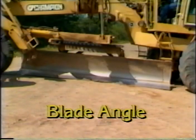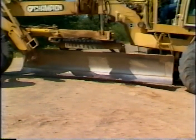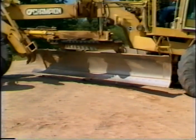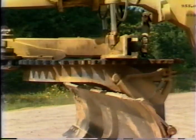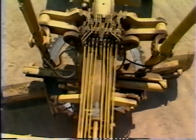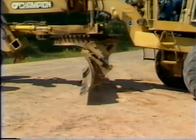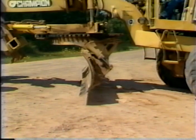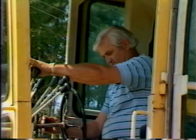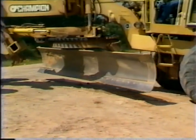The next movement is blade angle. On all graders, the blade is mounted on a circular mechanism, mounted on the center of the grader's frame. This mechanism can be rotated clockwise or counterclockwise throughout a full 360-degree turn. A blade perpendicular to the frame of the grader, or straight across, is considered to have a 0-degree spreading angle. For most jobs to be done using the motor grader, the blade angle varies from 15 to 45 degrees.